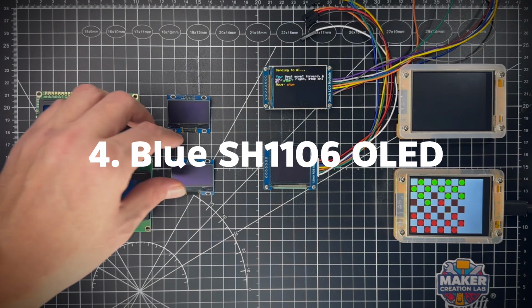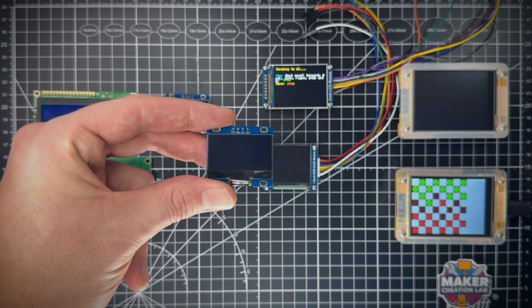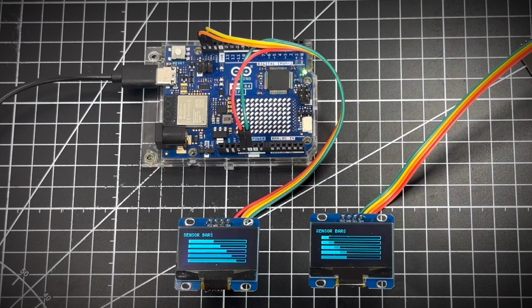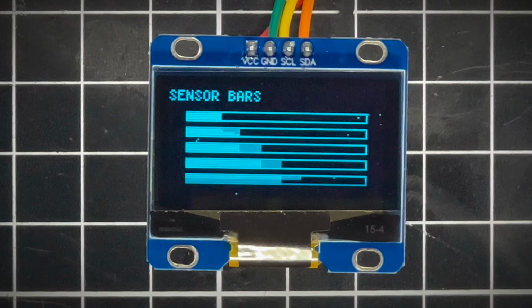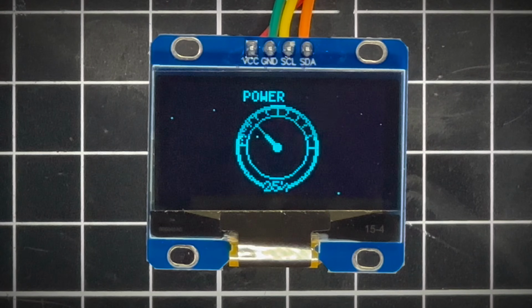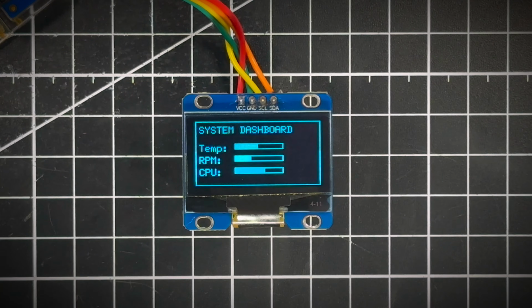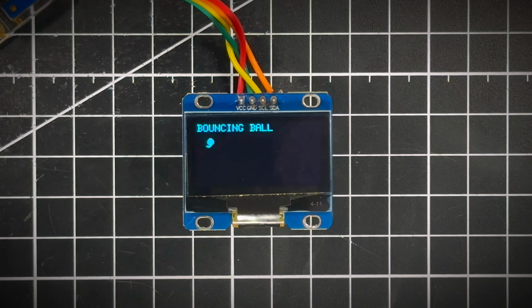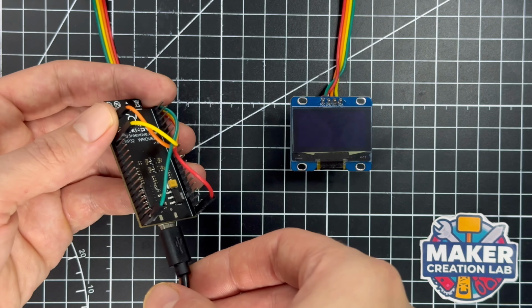At number 4, the SH1106 Blue OLED Display. At a size of 1.3 inches and a resolution of 128 by 64 pixels, using the U8G2 graphics library, this display has excellent font and icon support. Text looks sharp, animations are smooth on everything from retro video games and robot eyes to full sensor dashboards and command centers. This display also runs over the I2C bus, meaning you can connect multiple devices as long as each module has its own unique address.